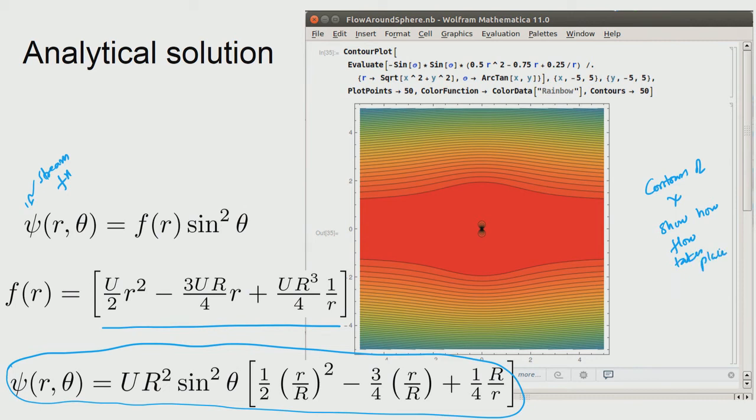So, what we have done here is a small one line MATLAB script to show you. You can see that we have this function, that is nothing but the f of r, and then we are converting the coordinate system from polar to xy here, and then plotting them in a range, and you can immediately see that the contours look like how we have imagined.